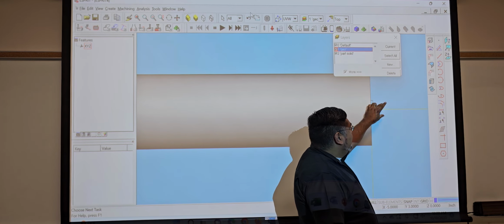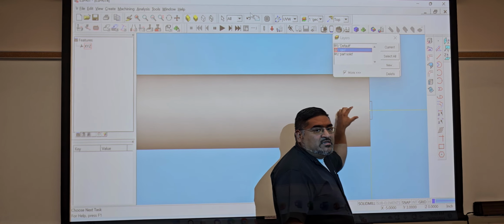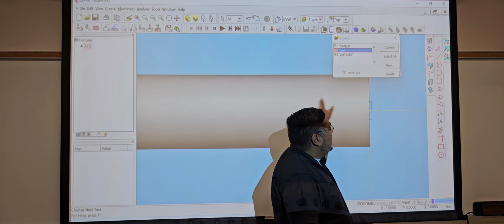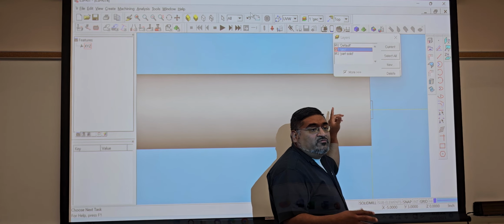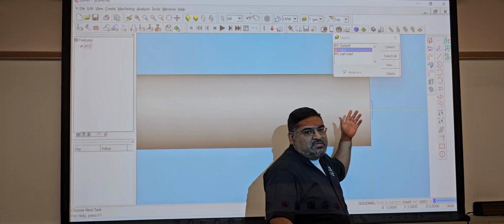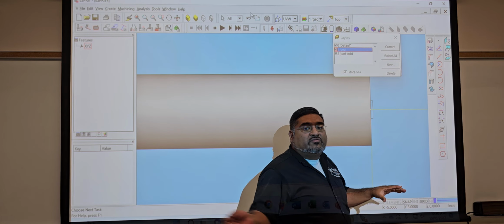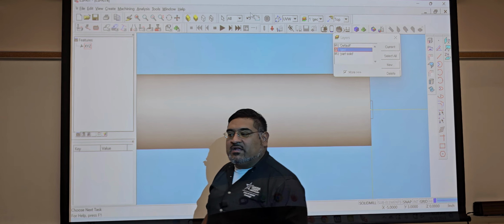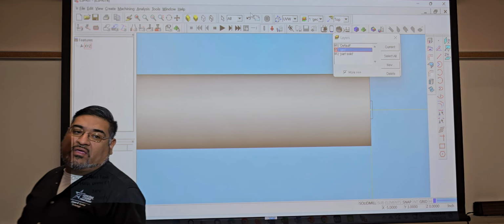Obviously, if I'm making that plug, the diameter on the inside is already like half an inch or whatever. So whenever the end mill came down, it hit some of that plug the first time, right? But it's plastic, so you can still use it for the next one. So it's just understanding what contouring does and what pocket does, correct?